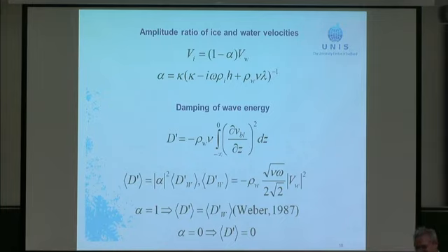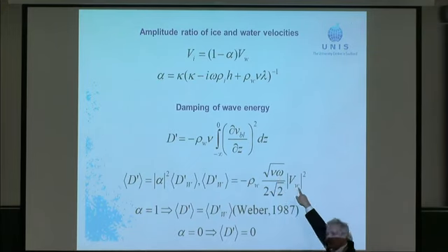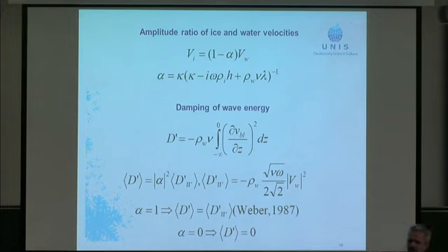No, but the dispersion knows about it. So here I use wave amplitude for the calculation. Here is velocity, and here I don't have the depth. I have only frequency and velocity outside the boundary layer. That's all. But when I consider wave energy, I express wave energy through the wave amplitude. And then there is a coefficient of proportionality between wave amplitude and this velocity, coming from the theory of linear waves. And this coefficient depends on water depth. Well, let's talk about it later. Could it be weakly dependent?